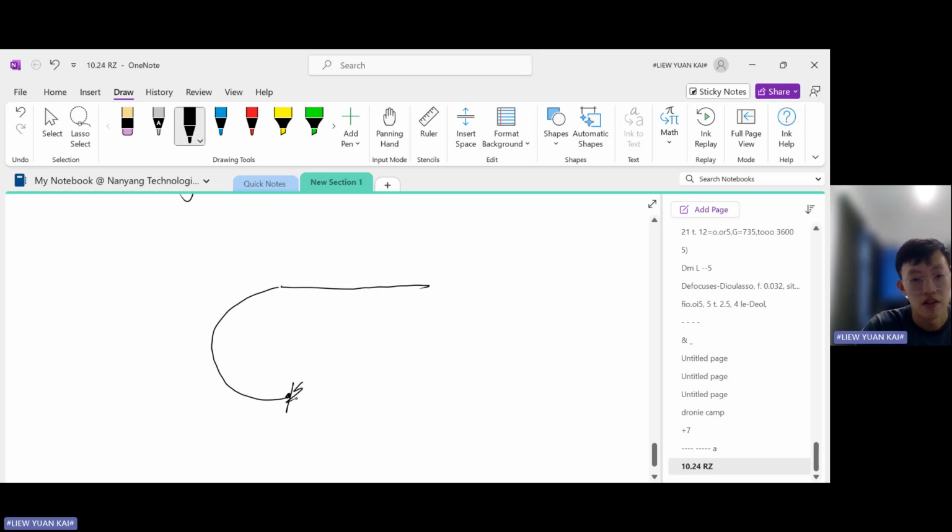Okay, this is the wall. We already removed the slot, right? Okay, so to draw the virtual load analysis, you remove every external load, and what you apply is the unit load that you want. So you see, we want to find the vertical deflection at point C, right? So in order to find the vertical deflection, I need to apply a vertical unit load.